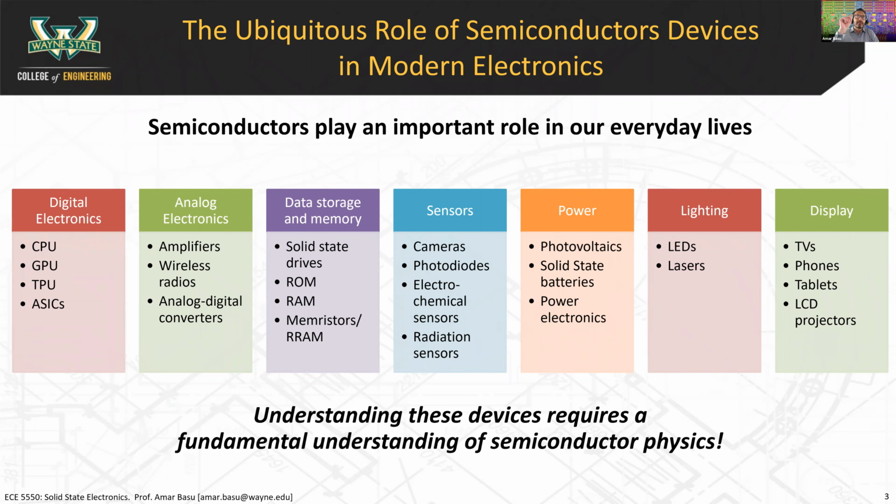The second thing, does anyone remember what the second thing was? The second advantage of shrinking down the transistor. I believe it runs faster. That's right. Exactly. Thank you, Clayton. So they run faster. Specifically in electrical engineering terms, they have smaller capacitances so that you can turn them on and off faster. So you can turn your switch on and off faster.